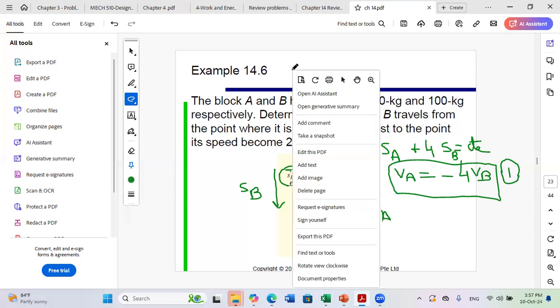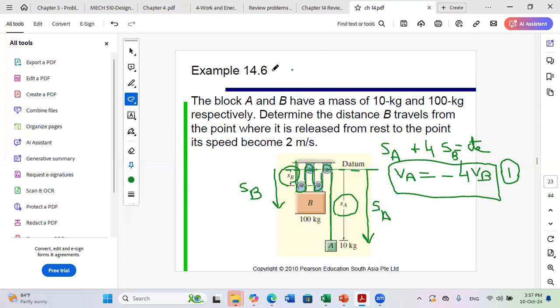We had the acceleration of A as unknown, the acceleration of B, and we also have the tension in the cable T that was unknown. And we want to solve for these different variables. Okay, so we wrote Newton's law for A, Newton's law for B.